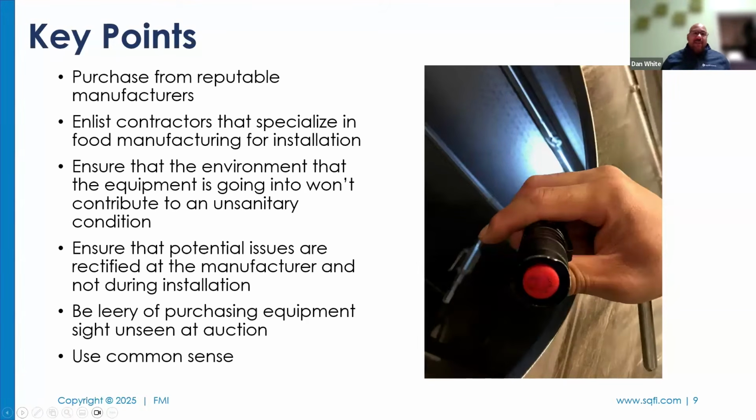The other one: ensure the environment the equipment is going in won't contribute to unsanitary conditions. I can't tell you how many times I've seen that, where you spend all the money on the equipment and put it in a room that is uncleanable. It doesn't matter if you have the best piece of equipment, if you can't keep the environment around it clean, you're shooting yourself in the foot.